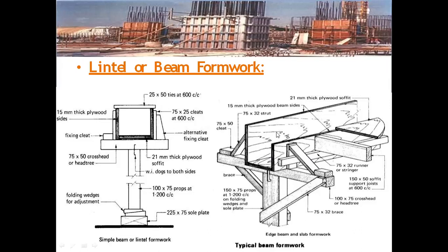When we pour the fluid concrete here, the load applied by the material can push these sides aside, so to avoid this, a strut has been provided, and this strut can be placed in position with the cleat here.